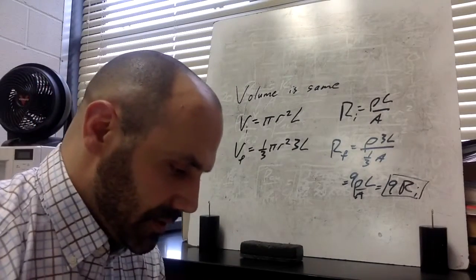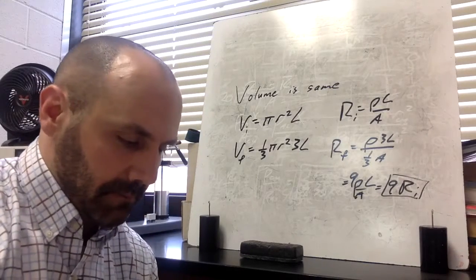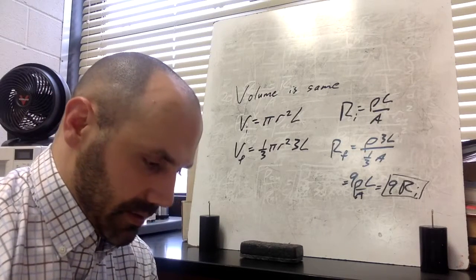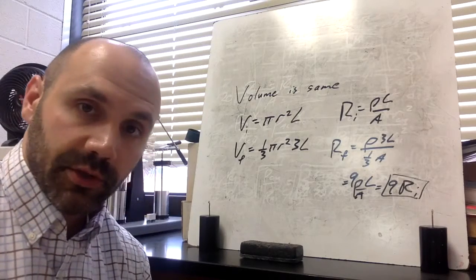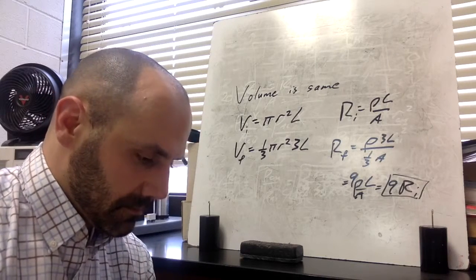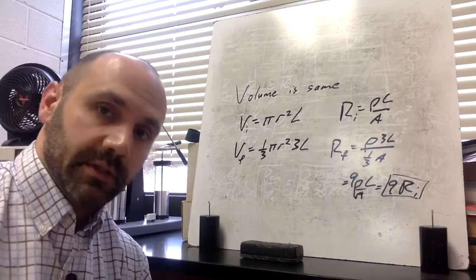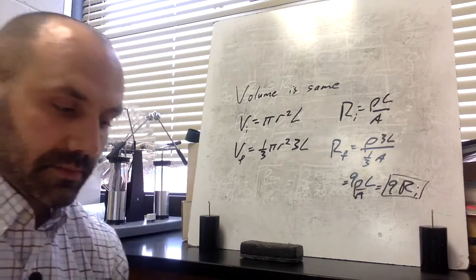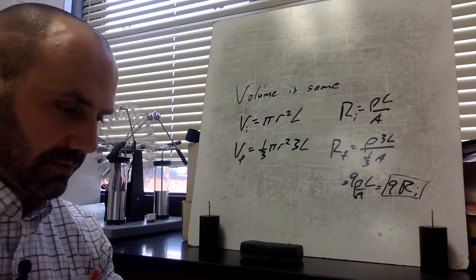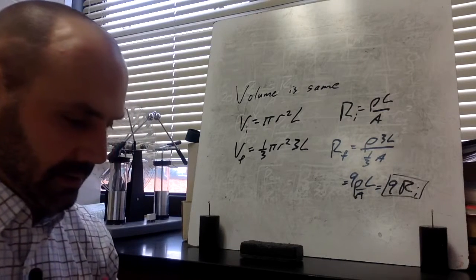Okay, temperature dependence. These are what I call the rat and the pat equations, because if you look at the middle, it looks like an A, rho alpha T minus T naught. So what are we talking about here? Rho naught and R naught are the resistivity and the resistance at T naught, the original, or some reference temperature. Okay? And then alpha is some temperature coefficient of resistance. And that can be found in those charts, temperature coefficient of resistivity, that kind of thing. And it's the same for resistance or resistivity. This works either way.